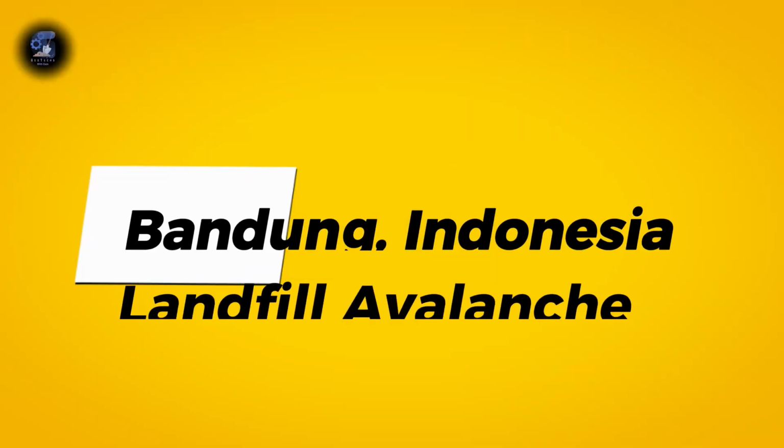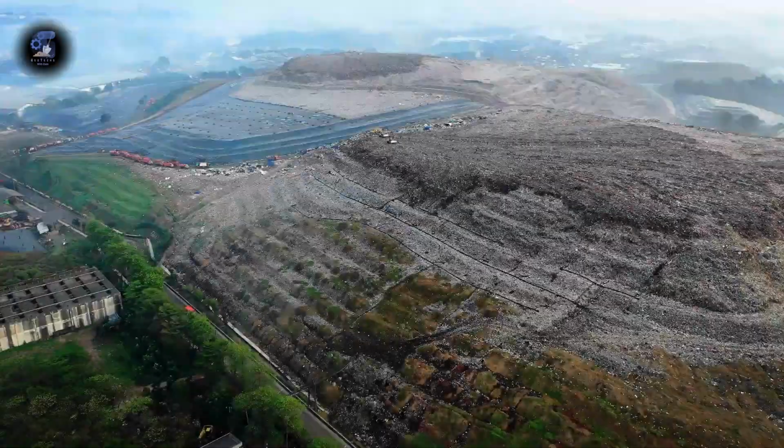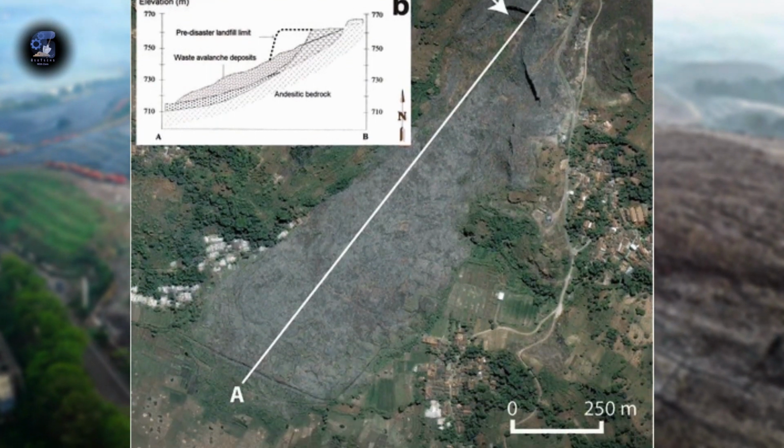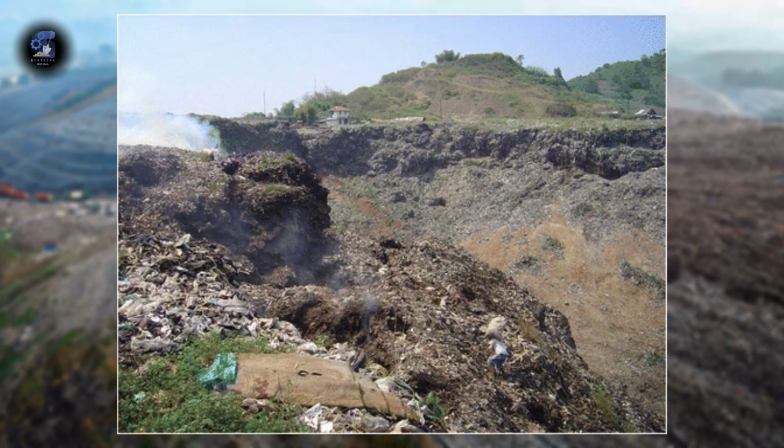A good example, but a tragic event to use as a demonstration, is the Bandung, Indonesia landfill avalanche. In the previous 3 days leading to the 21st of February 2005, the region of Bandung experienced torrential rainfall. In the early hours of the 21st, the residents around the landfill site heard 3 almost simultaneous explosion-like sounds a few minutes before the slide. The back analysis of the slide showed that the explosion was due to a sudden biogas release, and the heavy rainfall that increased the weight of the waste and pore water pressure were the 2 main triggering factors of the failure. So, the question is, how are modern landfills constructed to deal with the environmental and the geotechnical aspects?